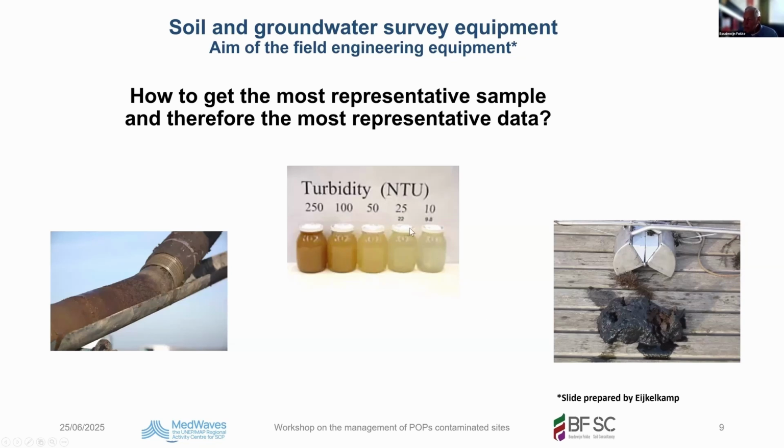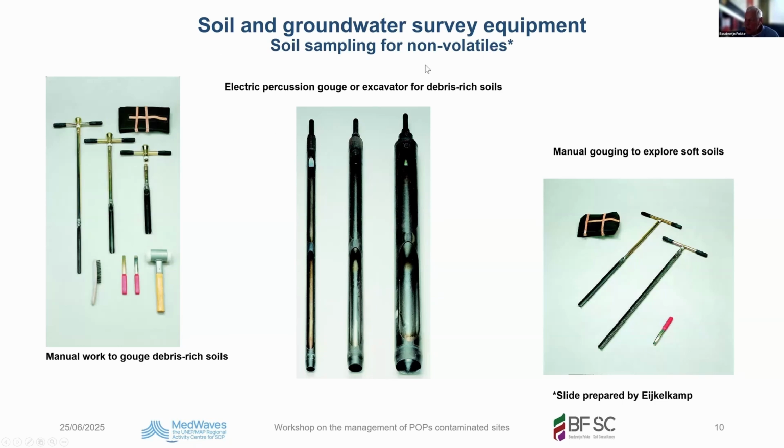Water, try to avoid that you have water with a lot of sediments. So on-site filtering of the water to be sampled is one of the methods to get a representative soil groundwater sample. These are pictures of sampling equipment for soil sampling for non-volatile components.